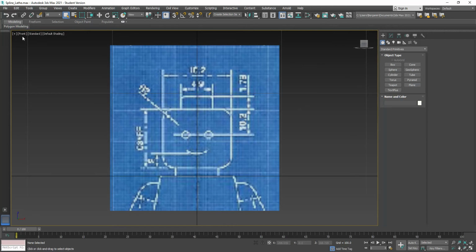So here in a front view, the right side of this dark black line, this would be positive X, this is negative X. We want to try to do all of our work over here in the positive space. There's many reasons why. A lot of the defaults will go from positive over to negative, so it's a good habit to be working on this right-hand side.